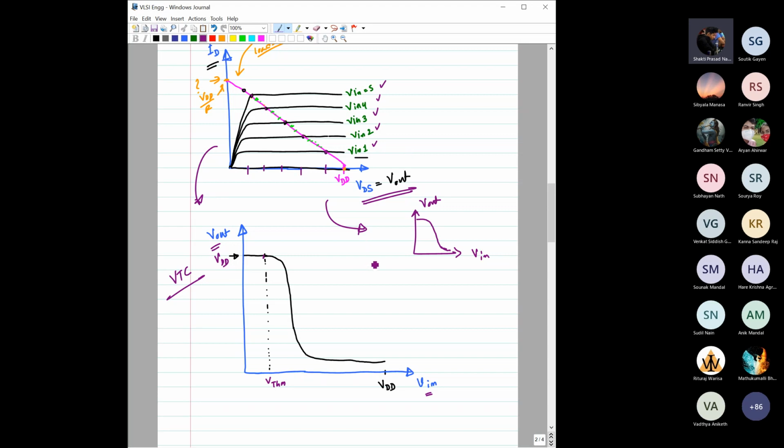Okay, so here I have one more question. What is this voltage? Quickly tell me. Aniket? Can you repeat which voltage you're asking about? Yeah, this voltage. So that's zero. Do you think that on this line I have made some mistake? Should it be at zero, or is it correct? No, sir, VDS should not be at zero. It's in saturation. Right, it cannot be zero, right?